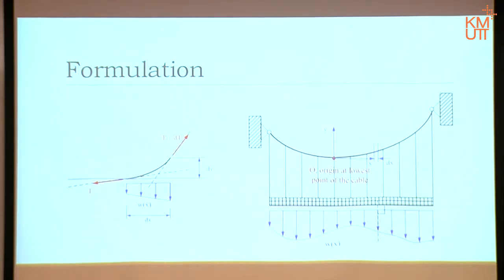Okay? Before we move on, because this is about mechanics, it's about forces, you can guess there will be sigma Fx, sigma Fy involved, right? Because these forces are not horizontal, not vertical, so we have to talk about the angle. The same thing, because it could be any place, I will name the starting angle theta. But you know that it is a curvature, meaning the angle will keep changing, right?